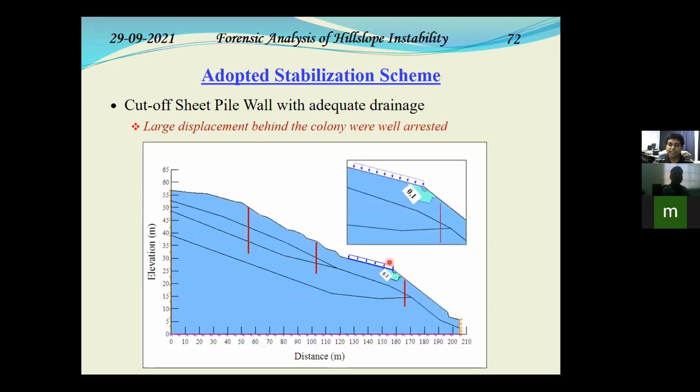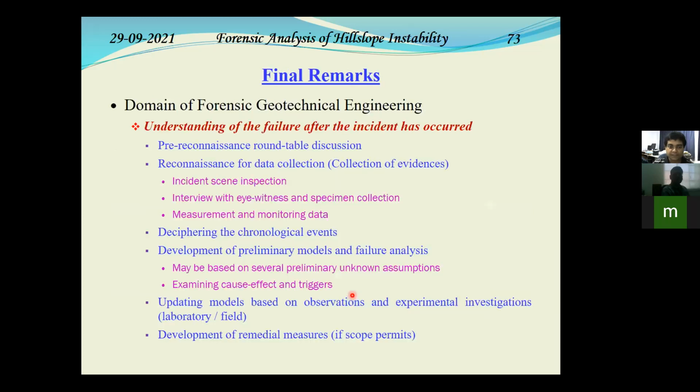Not only that, with that stabilization scheme, we could see that we could arrest the deformation in a significant manner, even at the steepest point of the slope. So not much deformation has taken place when this is analyzed with the sheet pile walls.